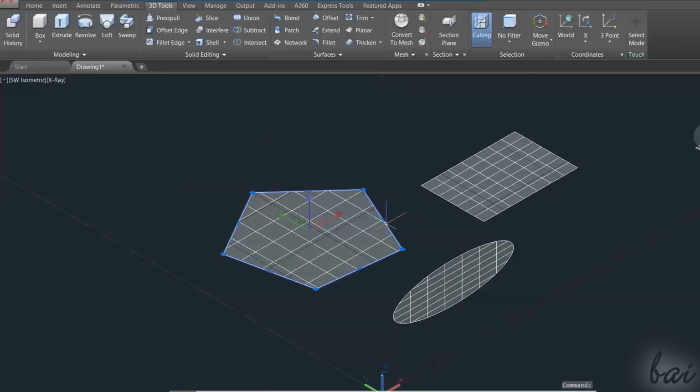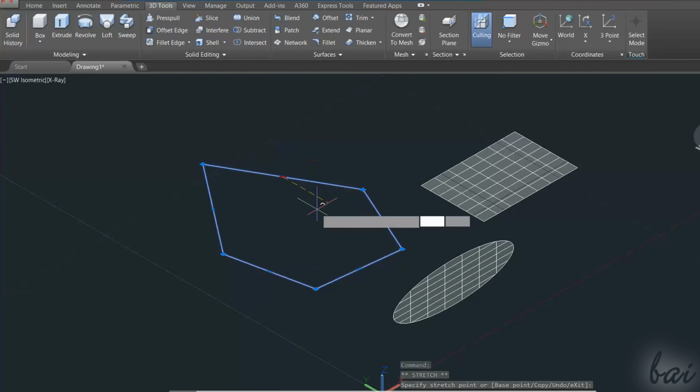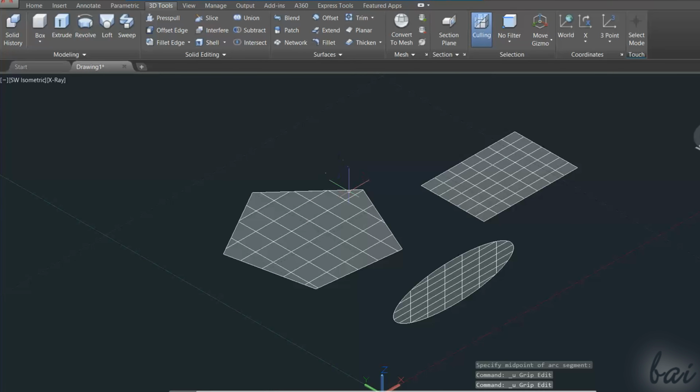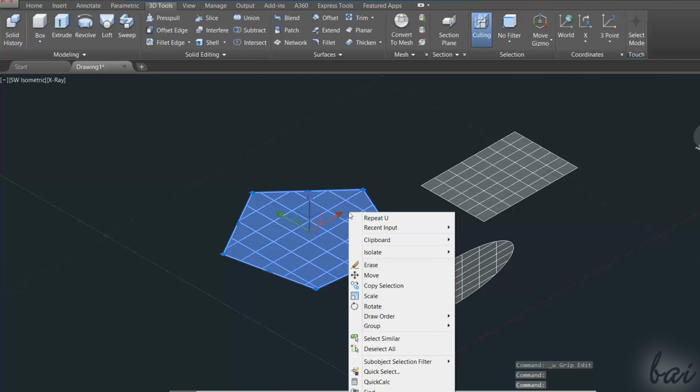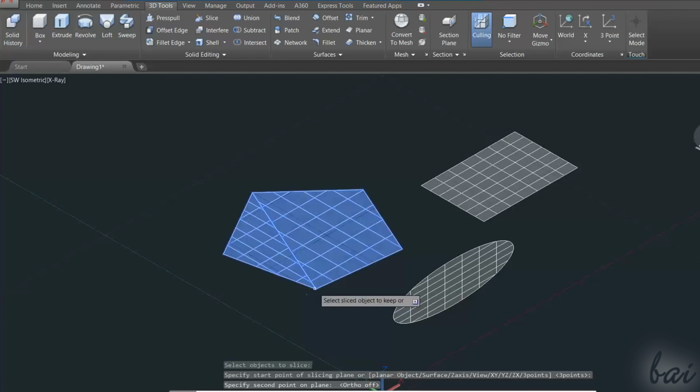Once the planar surface is created within a 2D path, this will get associated to its boundaries, which means that if the boundaries are edited, the planar surface follows. After creating the planar surface, remember to group it and its boundaries by selecting both, right-clicking and going to Group twice. In this way, you will edit both the surface and its boundaries when using any 3D tool.